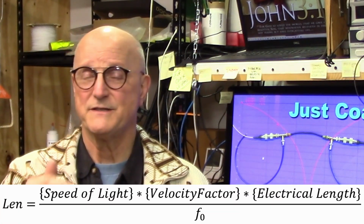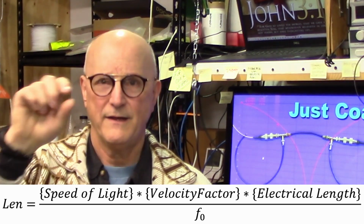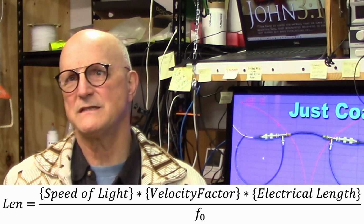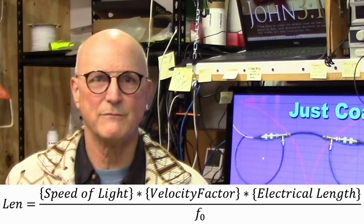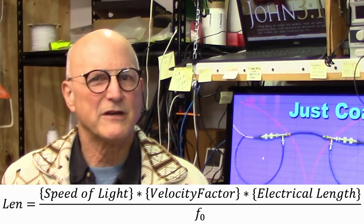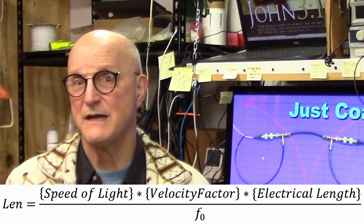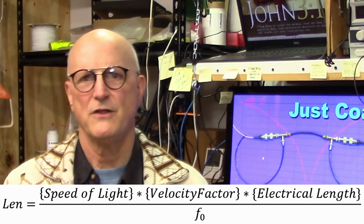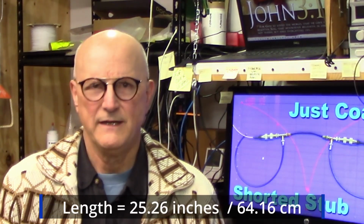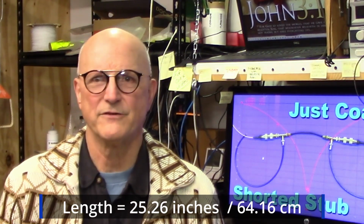The physical length is equal to the speed of light times the velocity factor times the electrical length, all divided by the frequency in question, where the units of the speed of light must be the same as the desired units to be used in measuring the stub assembly. I've placed the value of the speed of light in mega inches per second and mega centimeters per second in the description for you. In this case, the length of our stub assembly, including the T, the connectors, the coax, right out to the place where the inductor is soldered to our terminating connector, is 25.26 inches or 64.16 centimeters.